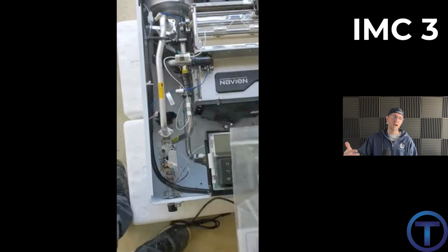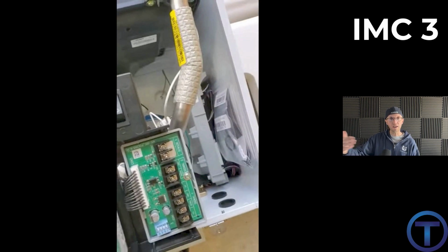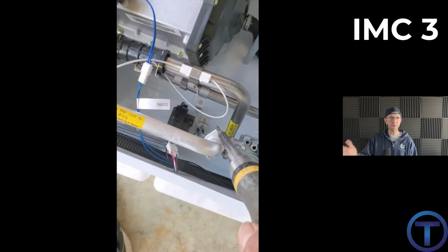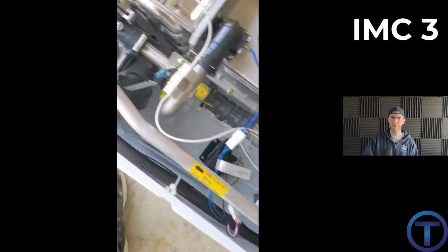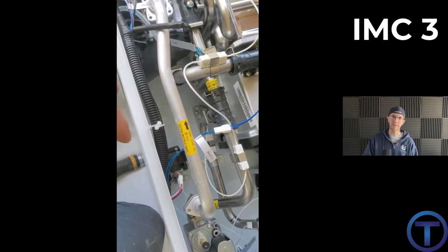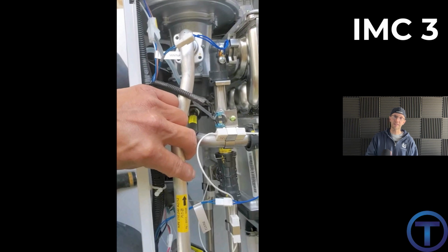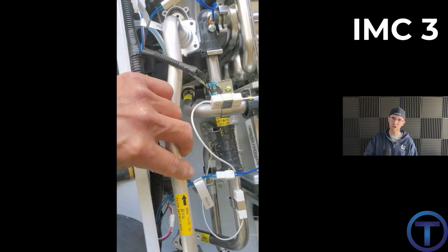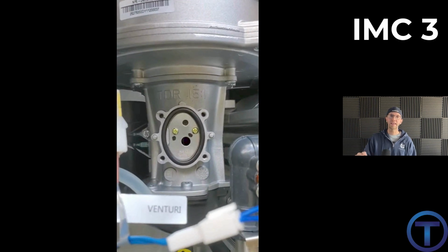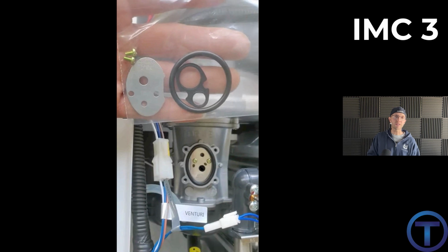Now, here's the thing. I made this mistake early on in my career of thinking that because this appliance, the Navien tankless, is capable of being installed at a natural gas or propane, that all I had to do was just tell the computer I'm using propane and it would already fix that. That's wrong. You got to get into the manufacturer's installation instructions, and it specifically shows you how to replace parts in there, the orifice, to take it from natural gas over to propane. So you have to do those steps.